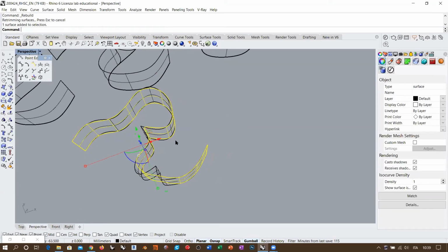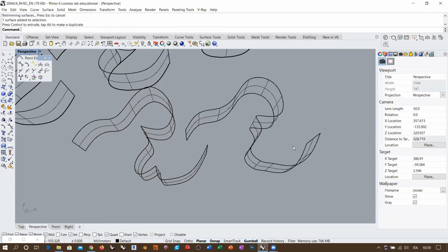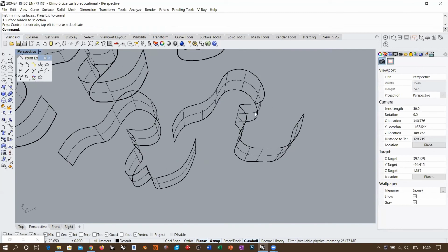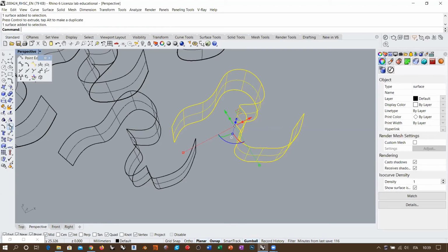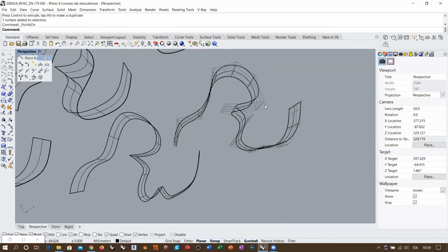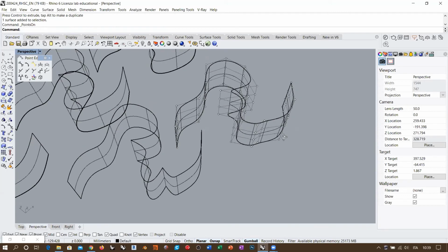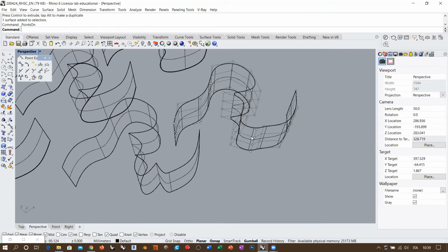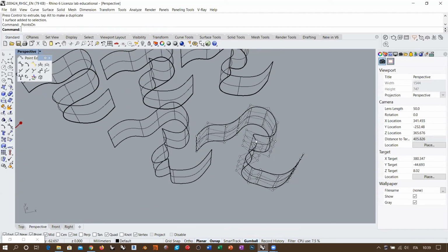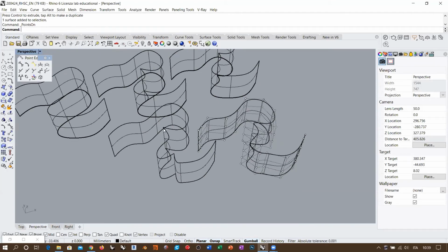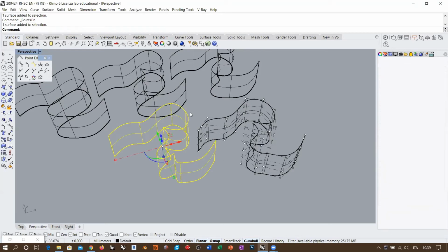this kind of result. And this result, as it redistributed the control points along the surface, eliminated the concentration of control points in the kink. So basically, it eliminated the two kinks that I had created. Okay, so if I take the control points, I have this uniform distribution of control points and surface spans, and the kinks are just gone. So if you want to make this kind of kinks along the surface and then have some kind of smooth deformation vertically, you cannot do this sequence of operations.